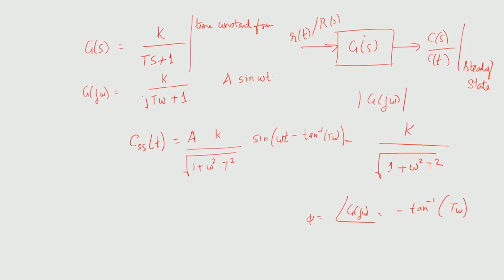Okay. So, this is actually straightforward now. Just look at what G is, compute its magnitude, compute its angle, and I can easily see what the output signal is. Each time I really wouldn't need to compute the inverse Laplace transform and do all that, substitute s equal to minus j omega, plus j omega, nothing. So, how does the magnitude change?